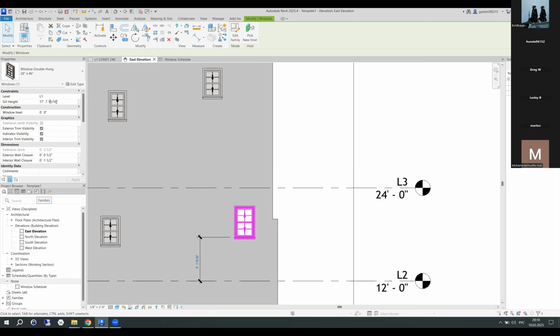Okay. So does anyone not know what your properties or your project browser is? Go ahead and now hit Control V and you can paste that other value. Now hit OK. And then you can change that level 1 to level 2. And it'll put it back in the same spot. There you go. And that'll be right there.